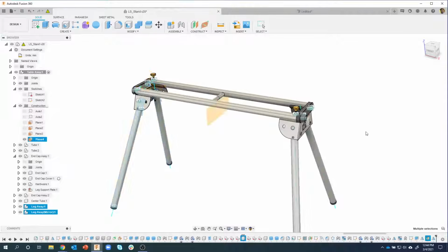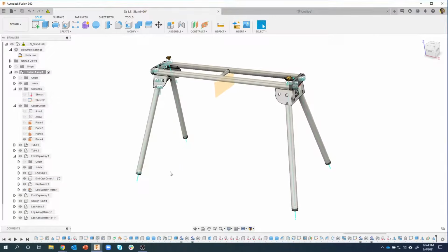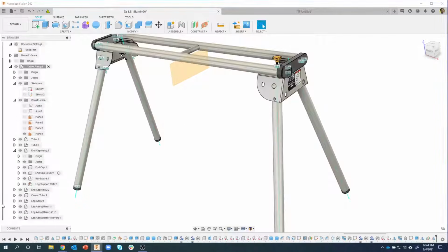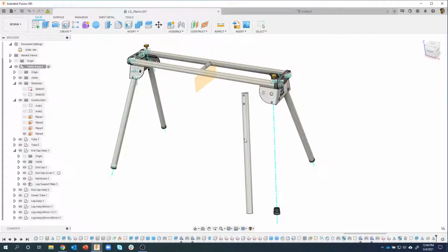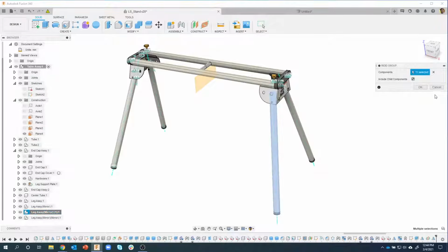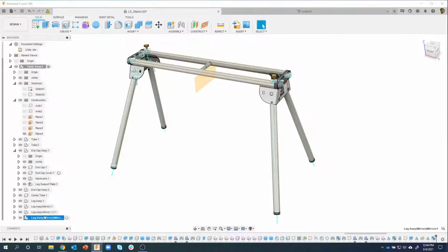I'll say OK. And you can really see why I love the grouping, right? This is a rigid group. Everything moved together. You can even see the axes that we used. And just like before, these are all individual. If I drag that out, they're not grouped together, but just like this, I can say rigid group. I'm happy with that. Rigid group, happy with that.